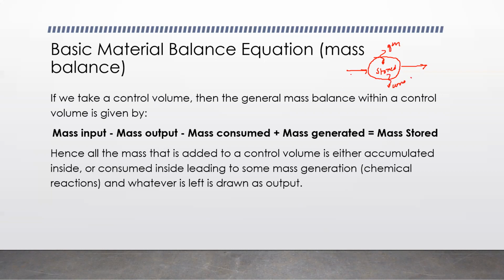Keeping all these things in mind, when we form a general mass balance equation, it is going to be mass input minus mass output minus mass consumed plus mass generated is equal to mass stored.